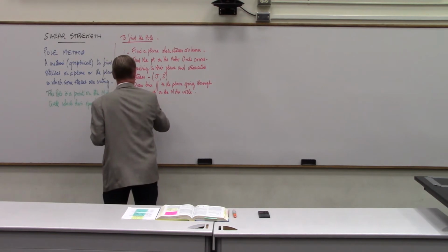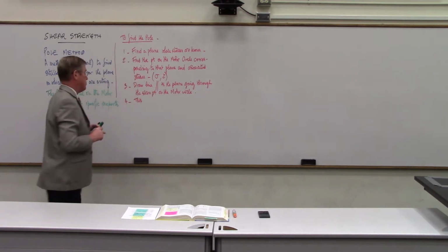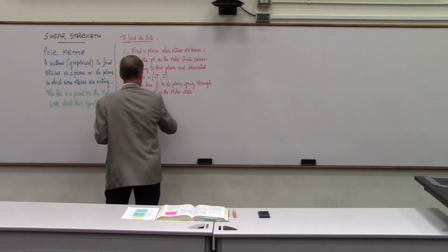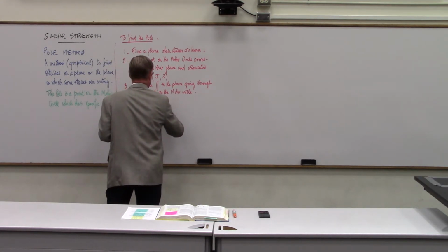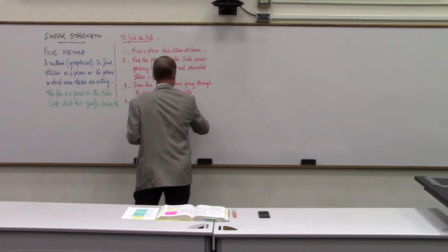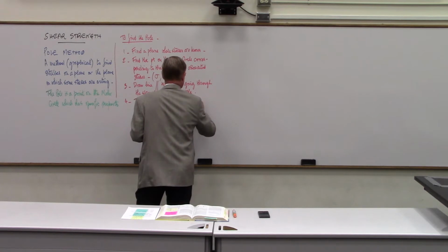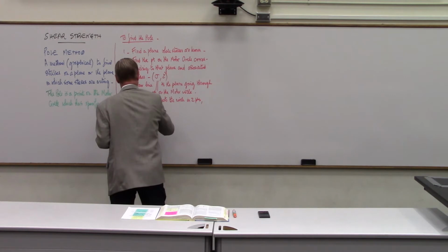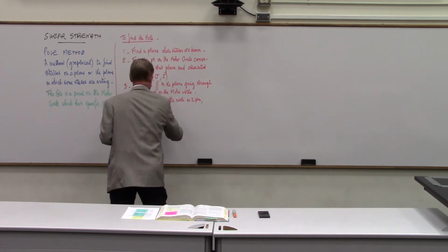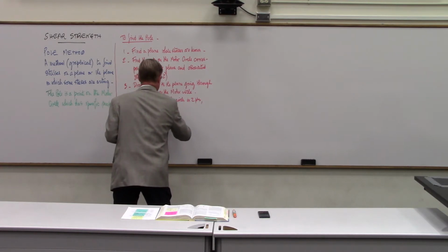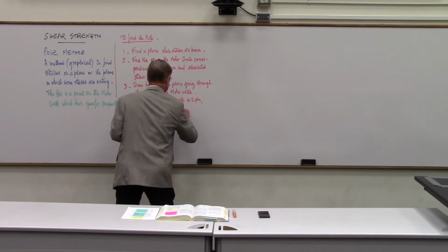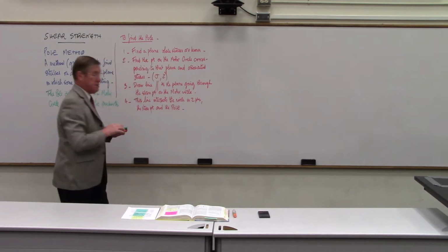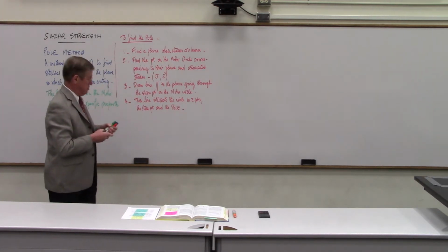this line that we drew in step number 3 intersects the circle in 2 points. One of these points is the stress point because you just drew the line through the stress point. So that point is on the Mohr circle. And the other point is the pole. So that's how you find the pole through this process.